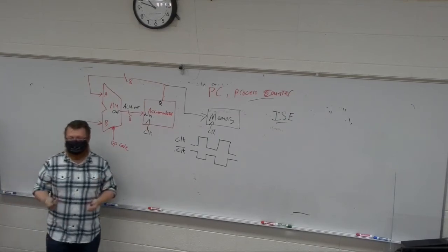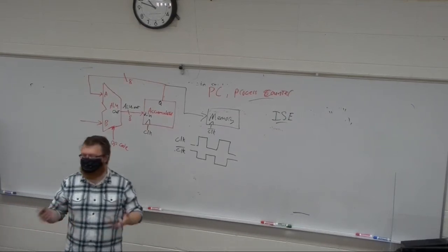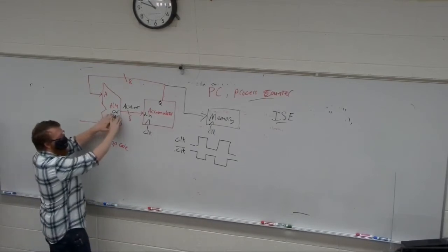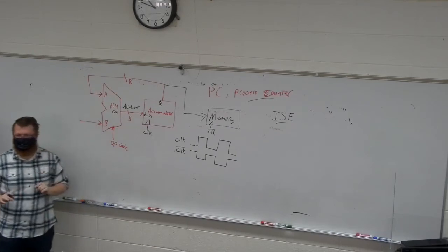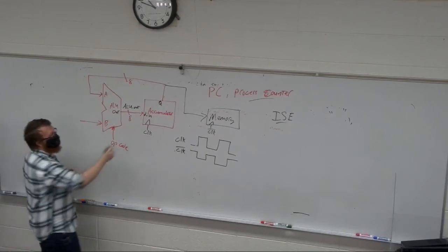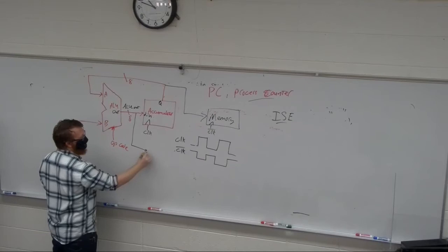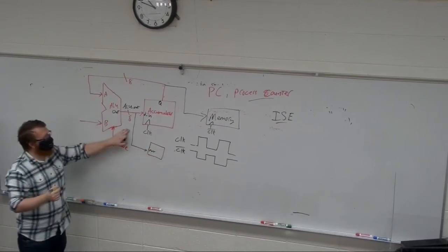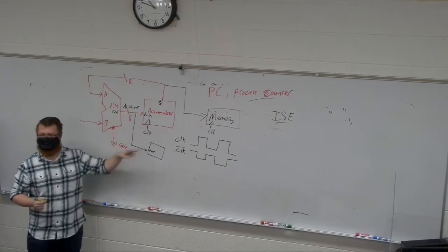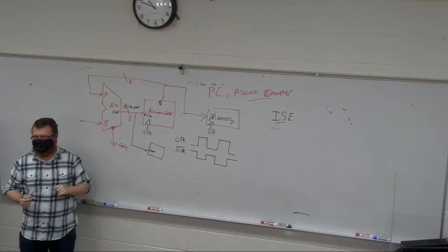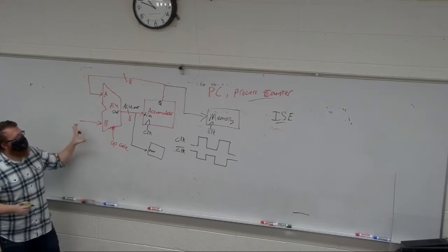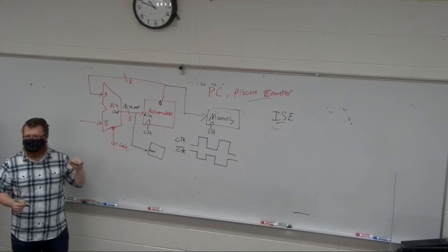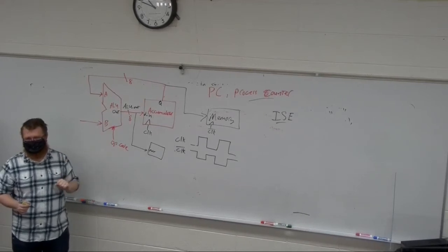This is a very important concept within VHDL, and in digital hardware in general: matching the port signal to port, right? And if we were to do something else with this, it still becomes clear that this ALU out is going to go to three different spots, right? So I highly recommend starting all of your designs with this, which we call a block diagram or a schematic diagram.